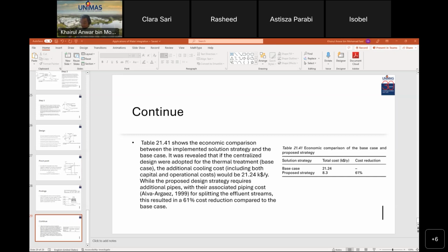However, the increase in temperature is not favorable from the viewpoint of water treatment. Higher temperature increases the corrosion potential in the cooling system. The corrosion rate increases with temperature and doubles for every 10 degrees C rise.